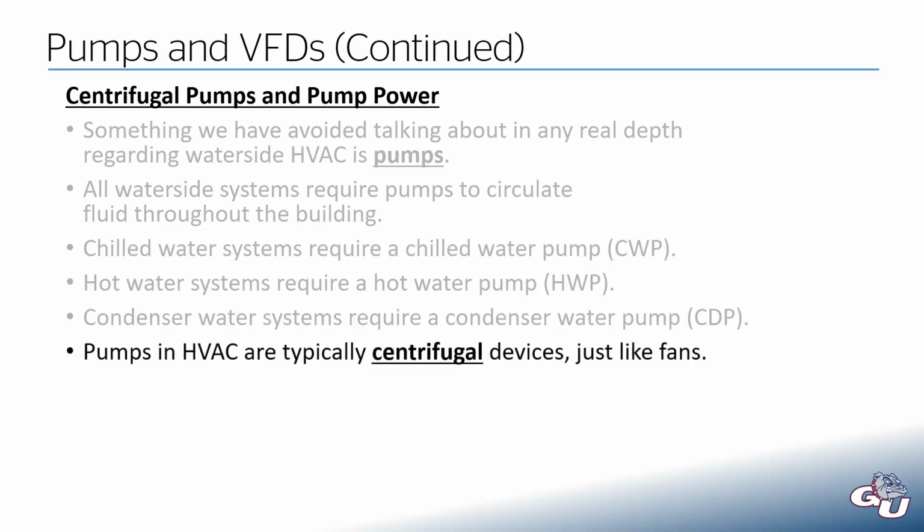Pumps in HVAC systems, most often, I mean 99% of the time, are centrifugal devices, just like fans. And when I say centrifugal devices, that means that they create flow in the system through creating a pressure differential, just like a centrifugal fan would.